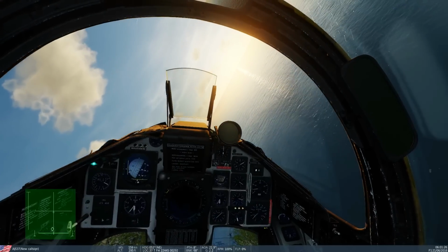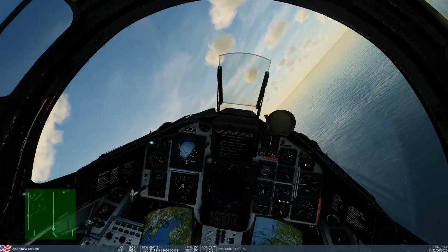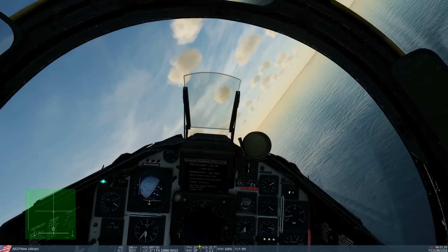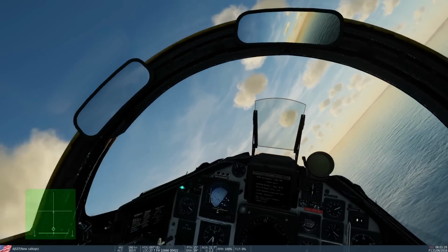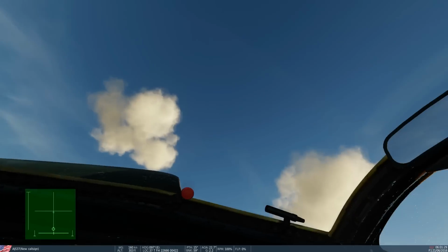160 knots. The engine started flaming out. Just ignore the engine flameouts. It's 23 degrees. SPARK allows me up to 23 degrees at about 160 knots. That's the first one done. Make sure you record the speed as well, RC, because that might be important. So the speed and the angle of attack.